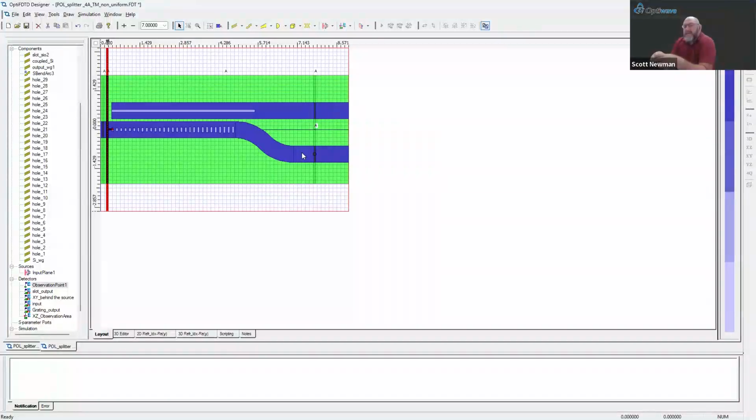So what you get at the end of the simulation is an average of your results, while the observation point is actually storing the field as a function of time for that single grid point. We can't do that over areas because the amount of data you're collecting is substantial. So we have this observation point, and this observation point is how I determine how many time steps to use. I'll run a simulation, we'll take a look at the observation point, and then based on that, I will either run a much longer simulation or I will proceed with my analysis.